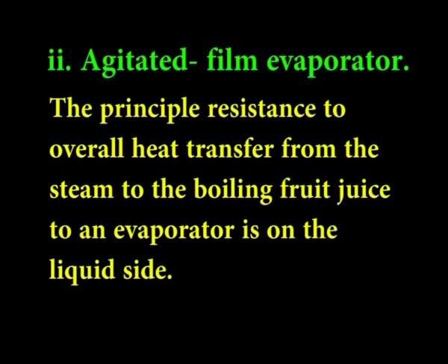Forced circulation evaporation can work either in natural convection, where the circulation of flow is induced by density difference caused by temperature gradient, or with forced circulation, where circulation flow is caused by a circulation pump itself. Agitated film evaporators are the state of the art design.